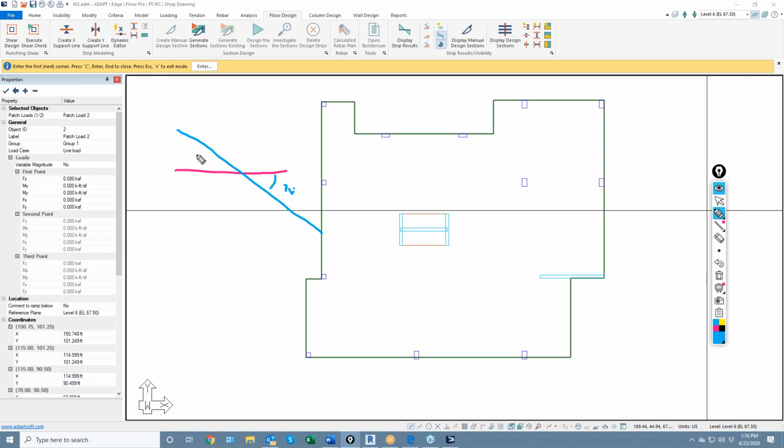So what happens is you might have another cut. I'll draw this in yellow. You might have a cut belonging to an X direction support line here for this yellow cut, and that banded cable really is going to affect the results essentially in both directions, where its primary purpose is really to affect the results for strips in just one direction.